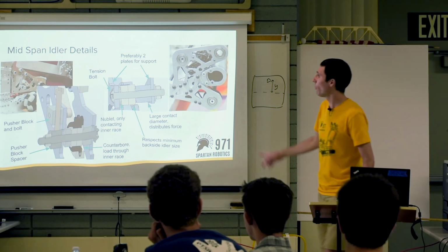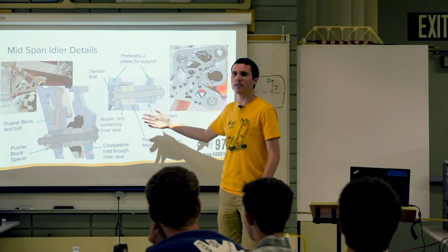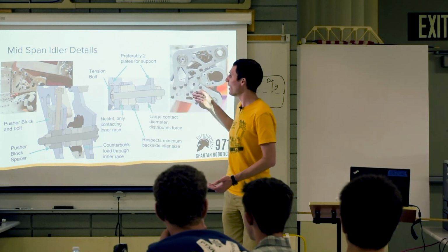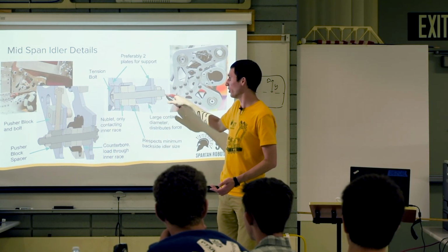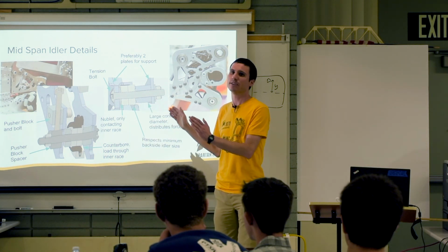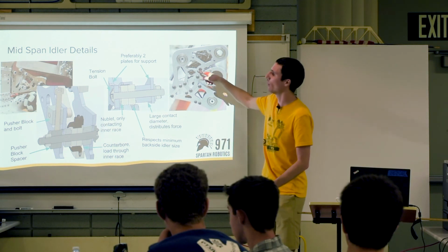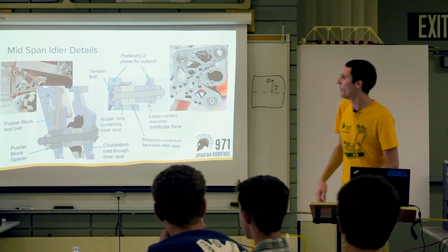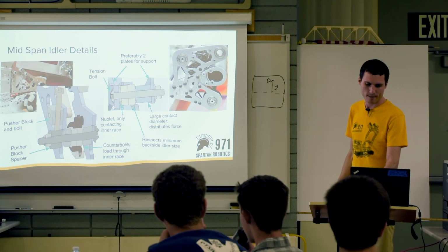Okay. I guess I should point out another note. When we look through designs on bearings or setups like this, I find it really helpful to do a cross section through it, so you can look at how everything stacks up, and make sure that all of these little details are taken care of. It's really hard to see these details by just looking at the overall system. You've got to slice down the middle and see what's going on there. And the same is true on shafts in regular gearboxes.